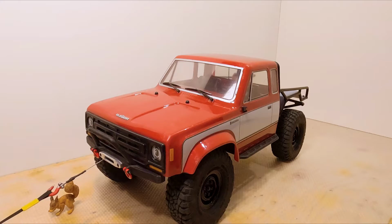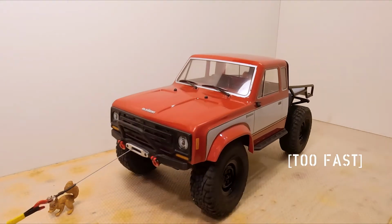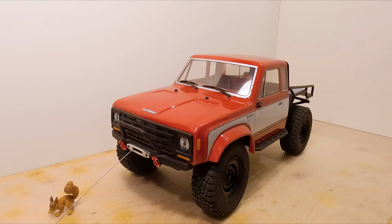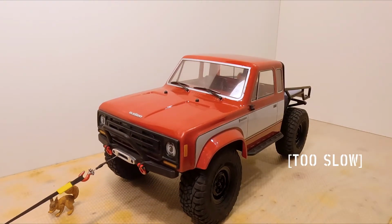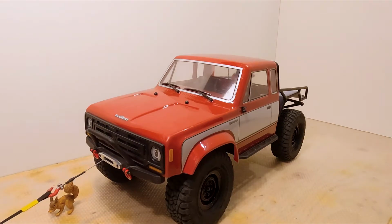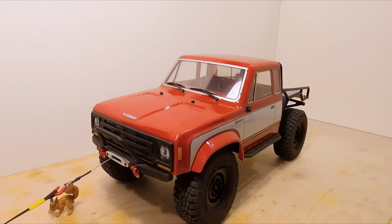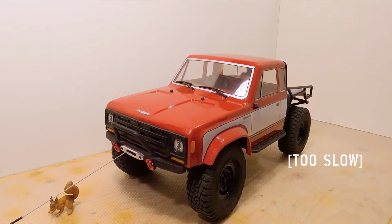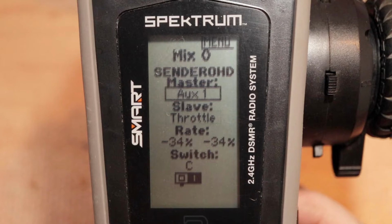With the truck on the ground, enable the mix and operate the winch. When spooling in, if the truck is driving forward too fast, you will need to reduce the forward rate. Or if the truck is driving too slow and the tires are not helping the winch, then you will need to increase the forward rate. When spooling out, if the truck is driving backwards too fast, you will need to reduce the reverse rate. Or if the truck is driving too slow and the winch line is too slack, you will need to increase the reverse rate. I will now show you how to set forward and reverse mixing to different rates.